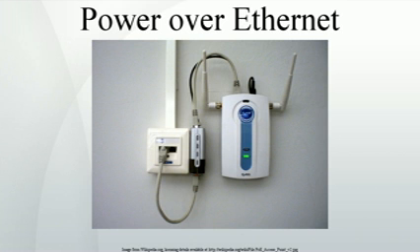The rules for this power negotiation are: PD shall never request more power than physical 802.3 class, PD shall never draw more than max power advertised by PSE, PSE may deny any PD drawing more power than max allowed by PSE, PSE shall not reduce power allocated to PD that is in use, PSE may request reduced power via conservation mode.